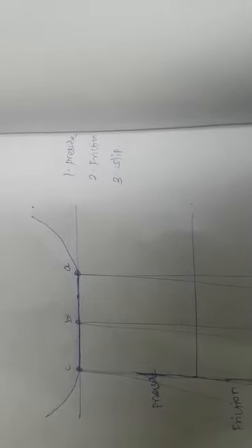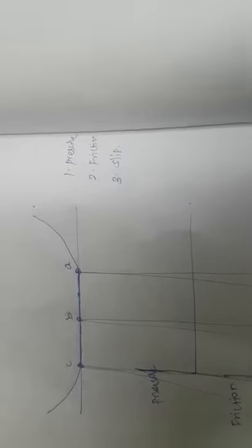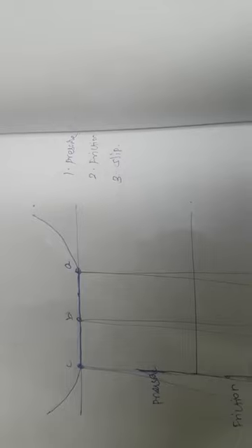So they cannot develop a frictional force because of viscoelastic nature and compliance. They just develop an initial pressure as they enter the contact patch, because the A point, the leading point, must bend to sustain a force. They just sustain the force, so they cannot develop a frictional force on the road surface, right? So the pressure must be very high and friction must be less compared to other points.